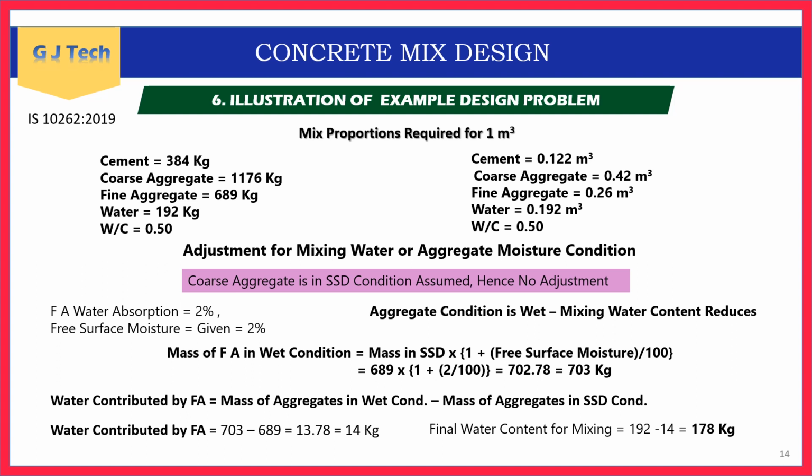Here in this current problem, they don't give any moisture of coarse aggregates. Hence, we can consider coarse aggregates to be in the standard saturated surface dry condition, but in practical aspects, there will be a variation of moisture in coarse aggregate also, that will be tested regularly before mixing a new batch of concrete.